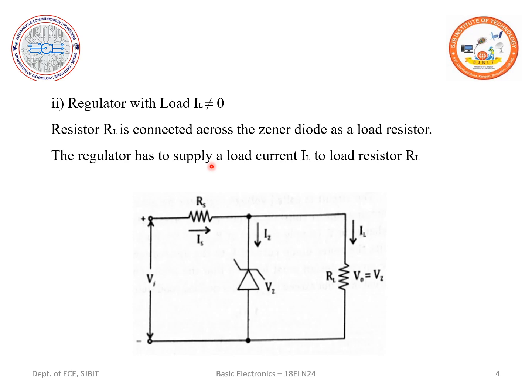With a load, let us study what is going to happen. Here, when you observe the circuit, we have the load resistance which is connected in parallel to the Zener diode, where we are going to tap the output across this load resistance. And I can say my V0 is nothing but my Vz. And when you look into the currents, you can see I have Is, that is, I have three branching currents here.